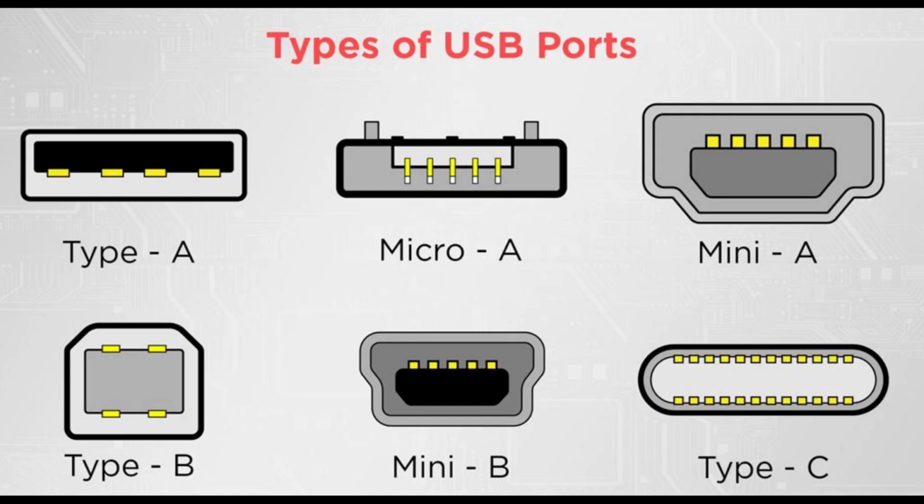The USB 3.0 specification defined a new architecture and protocol named SuperSpeed, aka SuperSpeed USB, marketed as SS, which included a new lane for a new signal coding scheme, 8B/10B symbols, 5 Gbit/s, later also known as Gen 1, providing full duplex data transfers that physically required 5 additional wires and pins, while preserving the USB 2.0 architecture and protocols and therefore keeping the original 4 pins/wires for the USB 2.0 backward compatibility, resulting in 9 wires, with 9 or 10 pins at connector interfaces. The ID pin is not wired, in total.